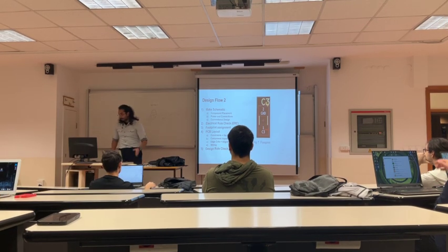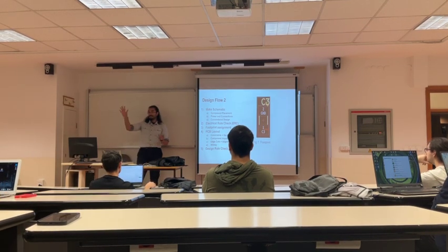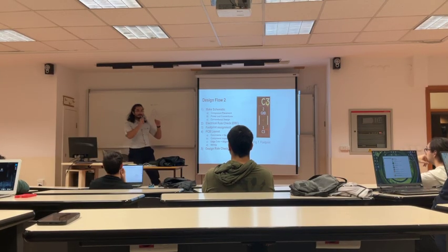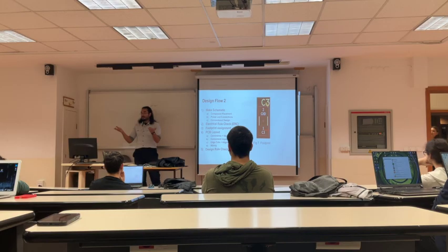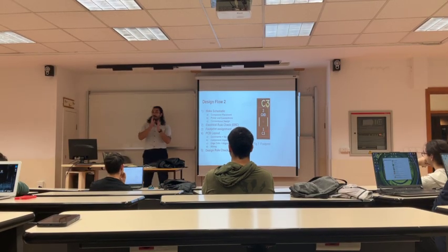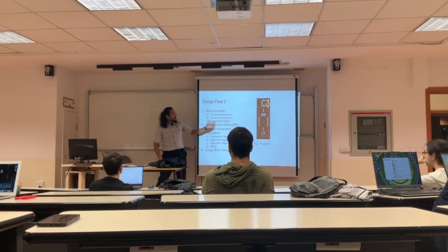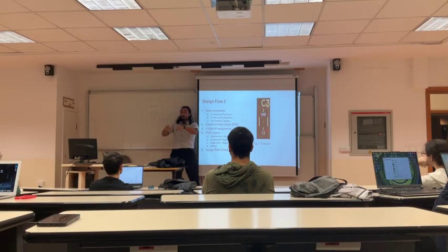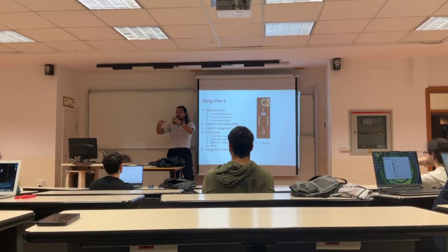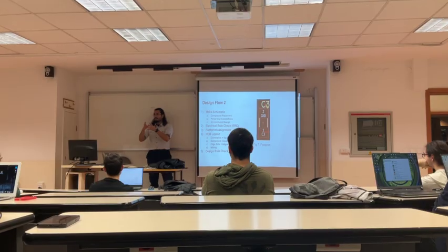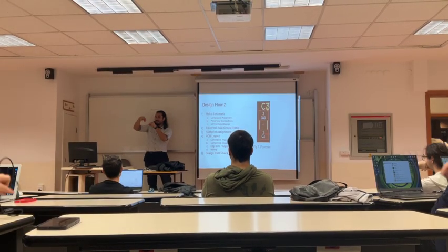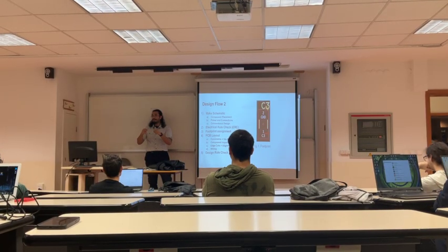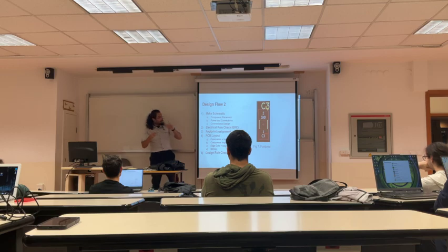So, design flow. We are going to do 5 things. You can remember that all throughout this. Make the schematic, okay? Then we are going to check if the schematic is correct, the second step. We are going to assign footprints. So what is a footprint? It is what we are going to put on the PCB to solder. So you have a schematic, but what does it look like in real life? The footprint is the thing that you put the component on. Okay. Did you get it?